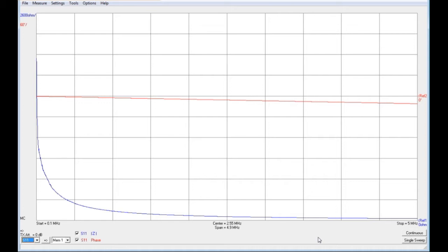Obviously, it's well within the capabilities of the VNA that we're using. The primary band for this VNA is somewhere, well, it says 1 kilohertz to 1.3 gigahertz, but the primary band is 1 kilohertz to 500 megahertz, and then there's an overclocked band from 500 megahertz to 1.3 gigahertz. So we're working in the primary band. That's good. We've got the best accuracy.